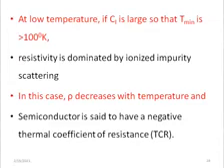So in this case, the resistivity will decrease with temperature. Whenever temperature increases, the resistivity will start decreasing. And any semiconductor that exhibits this property, that is the decrease in resistivity as temperature increases, we say it has a negative thermal coefficient of resistance. Negative because while the temperature increases, the value of resistivity is reducing, so it has a negative thermal coefficient of resistance.